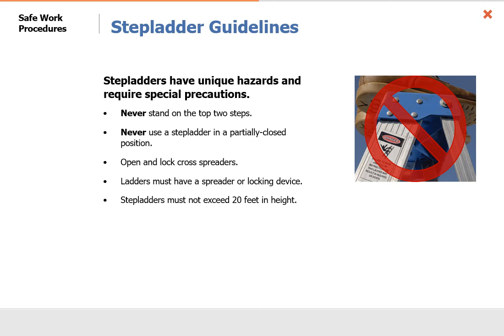Some stepladder guidelines. Stepladders have unique hazards and require special precautions. Never stand on the top 2 steps. Never use a stepladder in a partially closed position. Open and lock cross spreaders. Stepladders must not exceed 20 feet in height.